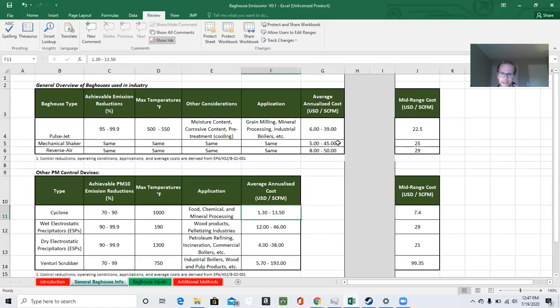Now, as you can tell, these baghouses are close enough in cost. They are higher, but if you look at $1 per ton pollutant removed, they're close enough that often EPA or your local Department of Air Quality will require you to use a baghouse as part of BACT. So that's why we would use them, unless they're not technically feasible, right, such as high moisture content.